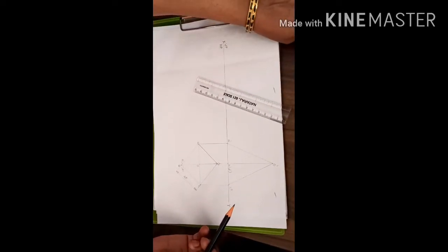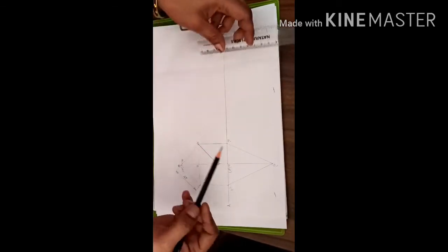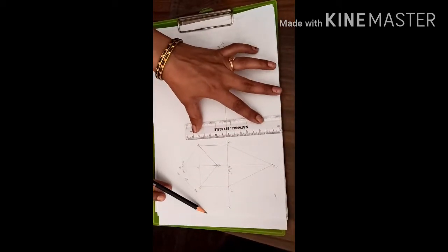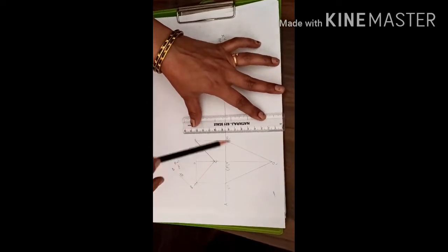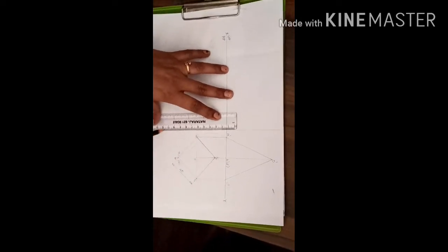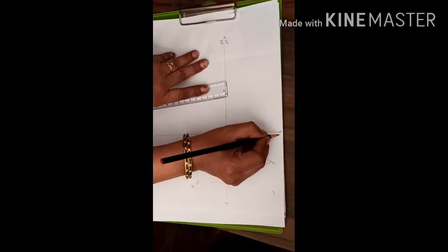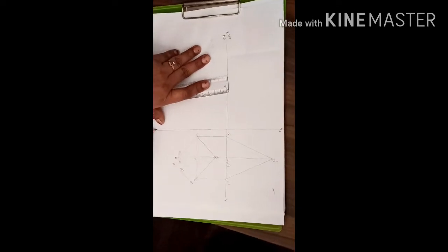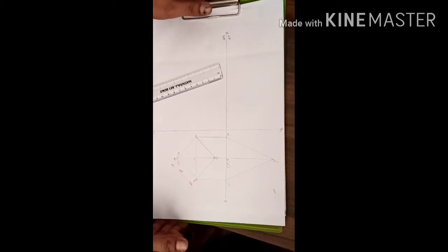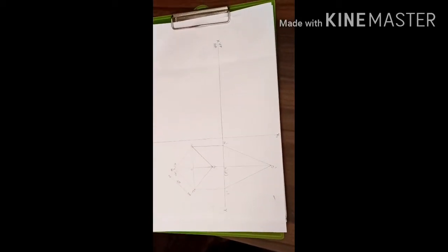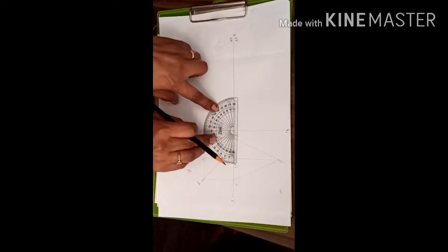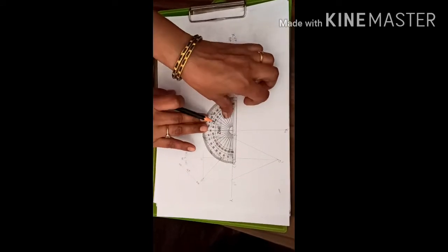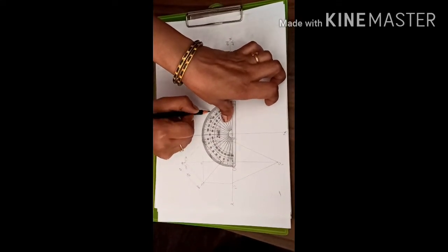Now we need to draw the side view of the square pyramid. So to draw the side view, we will draw the profile plane. So I will fix the profile plane at a certain distance. Let me call this the profile plane. The profile plane is denoted as x1, y1. So this is your profile plane. Now with the help of a protractor, we draw a 45-degree line from this origin where the xy line and x1, y1 line meet. So take an inclination of 45 degrees